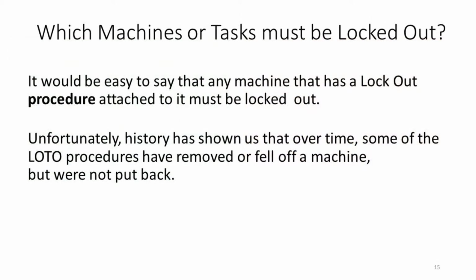Which machines or tasks must be locked out? Well, it would be easy to say that any machine that has a lockout procedure attached to it must be locked out. Unfortunately, history has shown us that over time some of the lockout tagout procedures have been removed or fell off the machine but were never put back.